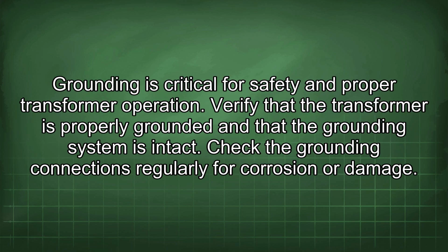Grounding is critical for safety and proper transformer operation. Verify that the transformer is properly grounded and that the grounding system is intact. Check the grounding connections regularly for corrosion or damage.